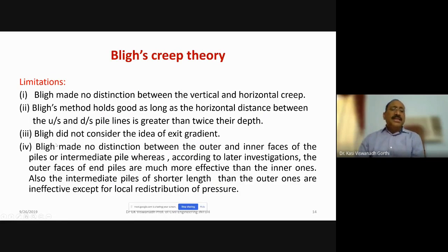Then another limitation is that Bligh did not consider the idea of exit gradient. We are not talking anything about the hydraulic gradient here. Hydraulic gradient theory has been discussed separately, and Bligh did not consider that. Bligh made no distinction between the outer and inner faces of the piles or intermediate piles. This is another important observation made, which has been a limitation for Bligh's theory.